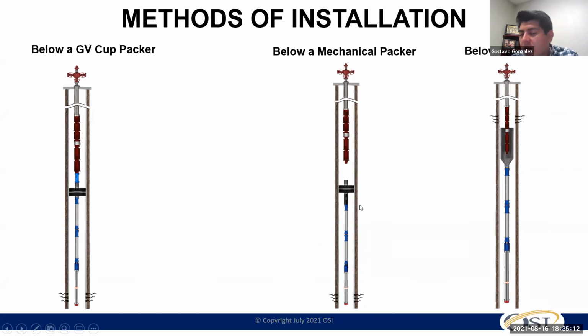either a desander, screens, gravel pack, whatever you want to do. But the perforation has to be underneath that packer, so fluid can go through your sand control method and go up. You have to use an on-off tool, so you can go back, set the packer, remove the tubing, pull it back, and go back with my ESP. But in that case, I keep those two sections separate.